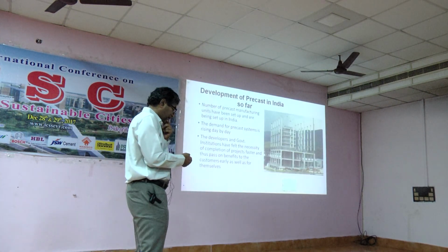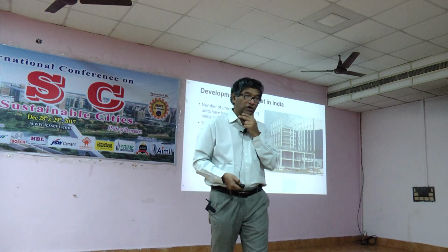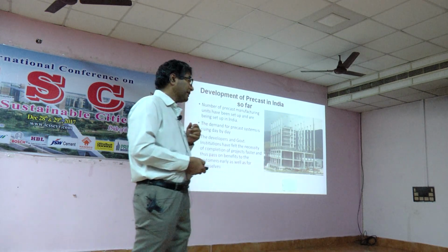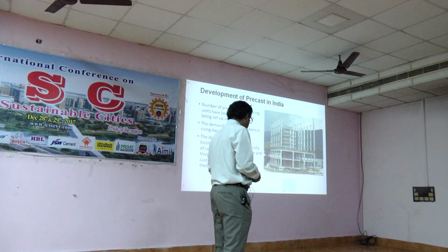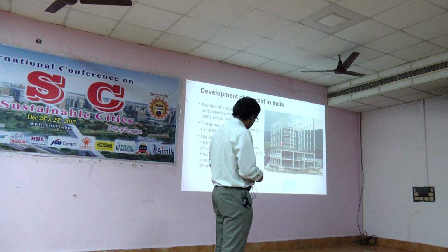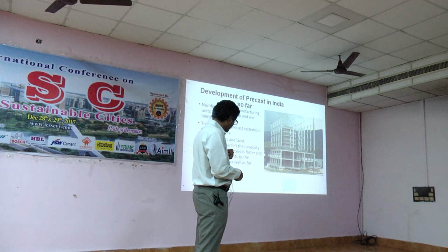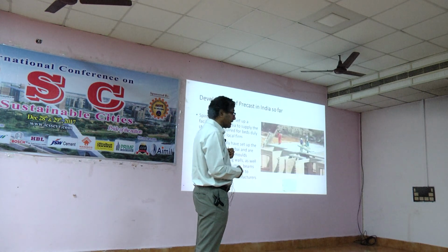Precast is taking shape wonderfully throughout India. We are going to hold one more conference here in Siddharth Engineering College on 19th to 21st. You can also see some more examples of precast and composite construction. Here you can see a 3-story column, 2.5-story column brought to the site at one go, and then they are just connected at this point. So this is the advantage of precast. At a time you can do that.